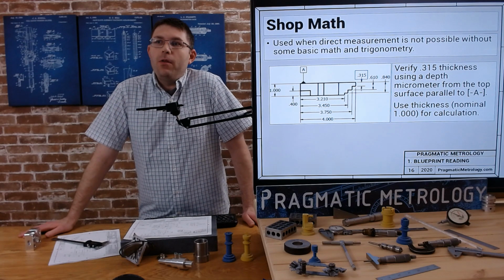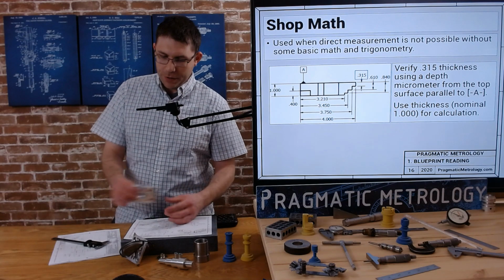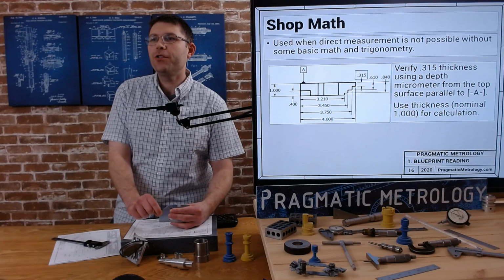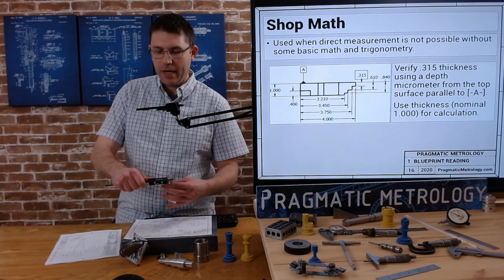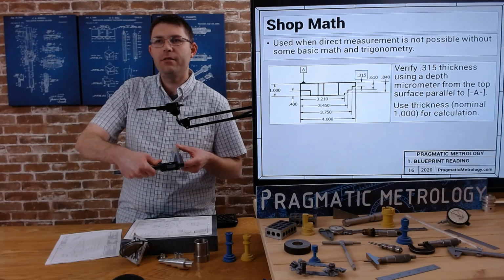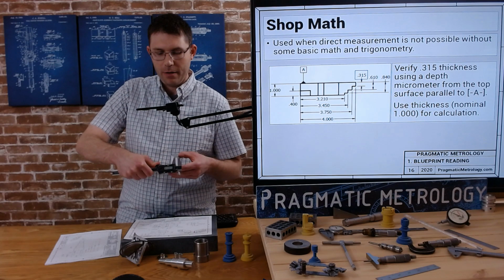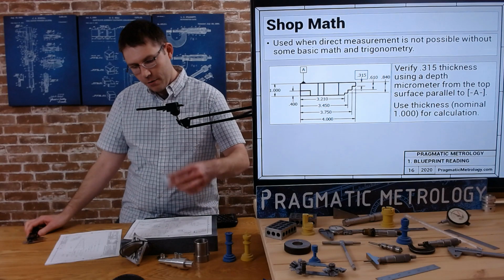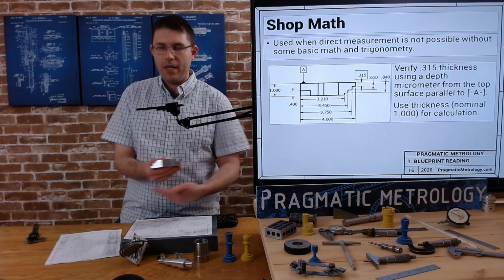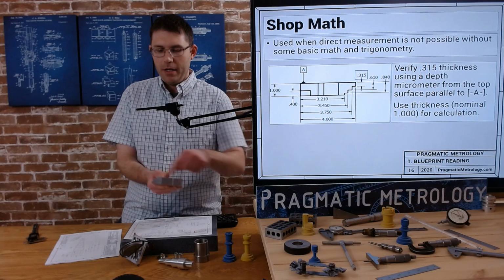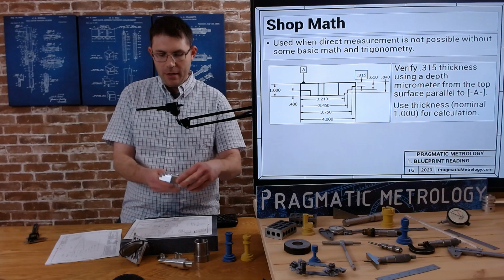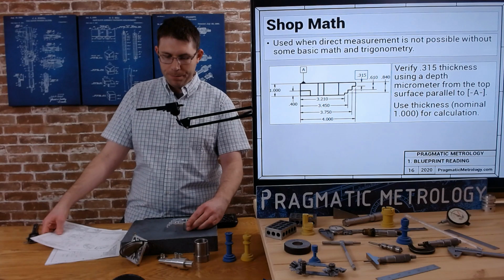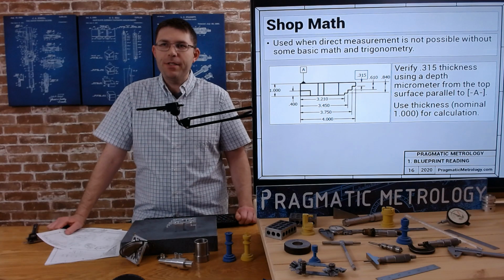So here's an example. That 3/15 step thickness in the top view here, if you're going to measure that the way it's called out, that's a simple caliper check from the back side. There's nothing involved. But let's assume for a second that this is being machined out of a piece of aluminum, and this is the operation that starts first. It goes around, it does the slots, and it's still in the machine. The backside hasn't been cut yet.